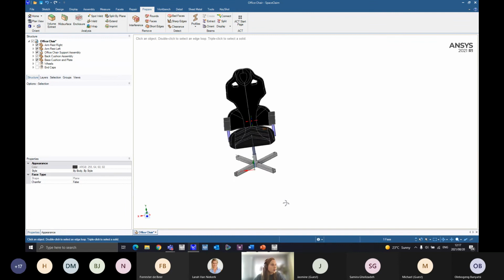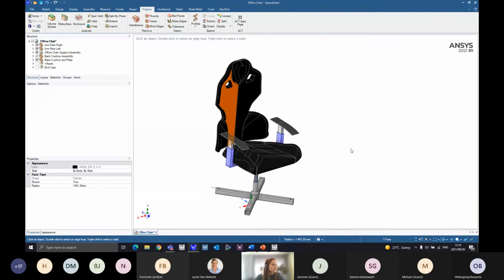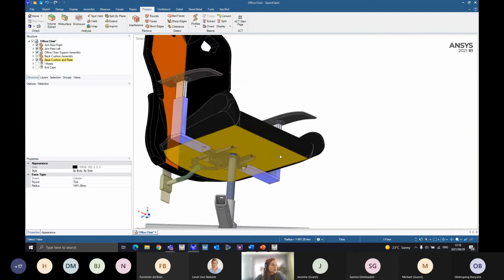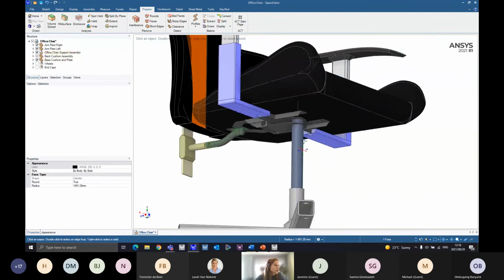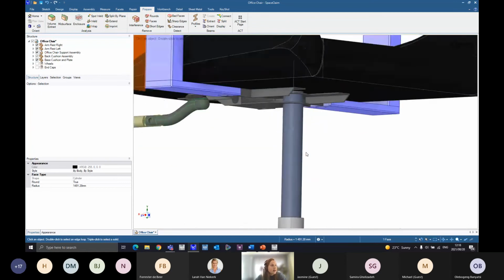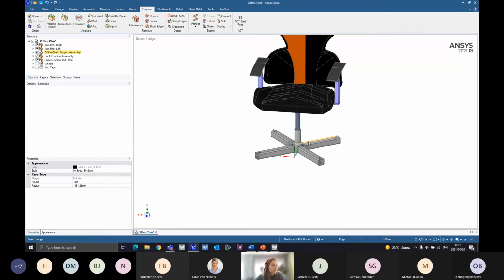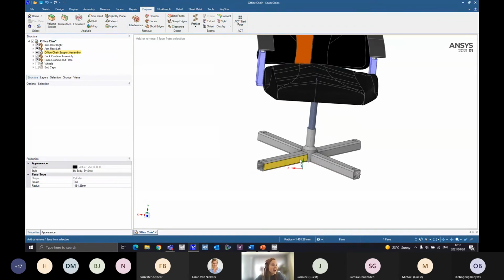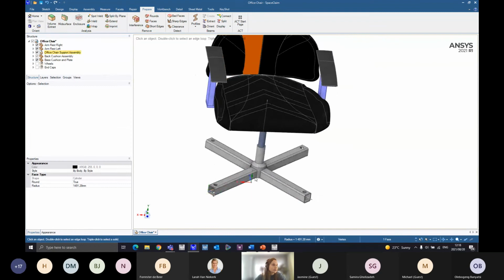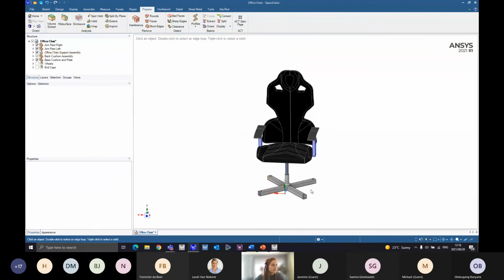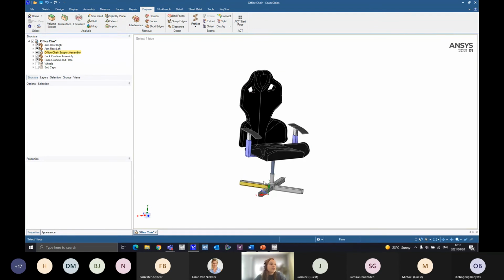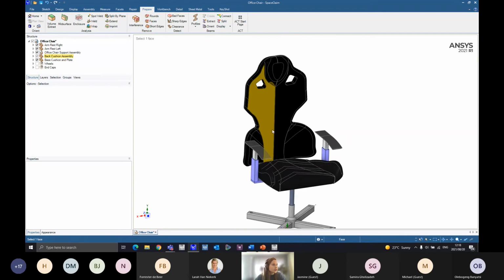So in this case, I thought the cushions or the support of the office chair would probably be best as a solid, and most of these supporting plate-like structures are probably Midsurface, and then the feet support, I'll call them beams because they are beams, I will represent as beam elements. So in that case, it would be the most efficient, and it would still represent the geometry as you generate the mesh. Okay, so after this, I'm going to start with the 3D geometry perhaps.